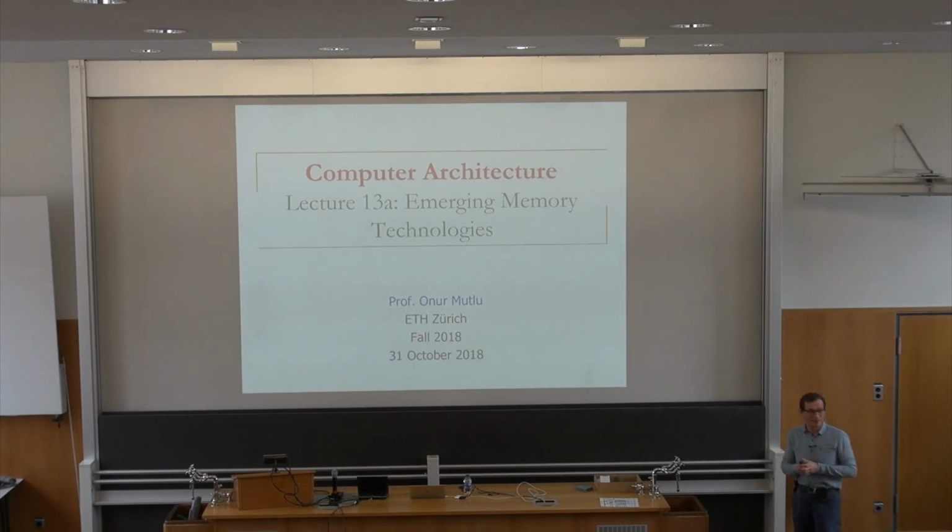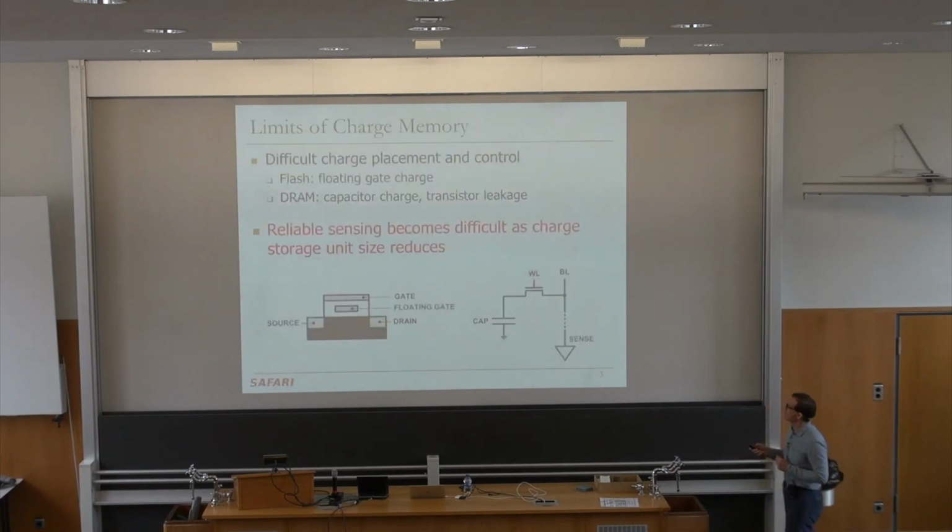And if you remember, when I talked about processing in memory, I said that some of these emerging memory technologies that are non-volatile, that do not need to move data when you actually need to operate on it, can be much more efficient, fundamentally much more efficient. And we're going to cover some of those technologies, even though I'm not going to spend a lot of time on how to do processing inside the emerging memory technologies. But you can imagine things like Ambit, for example, that we discussed, analog operations that we tried to do in DRAM that brought us a lot of performance. You could actually do that inside these memories that are non-volatile without moving the data, without doing the RowClone operations internally. Okay. So let's talk about what these are.